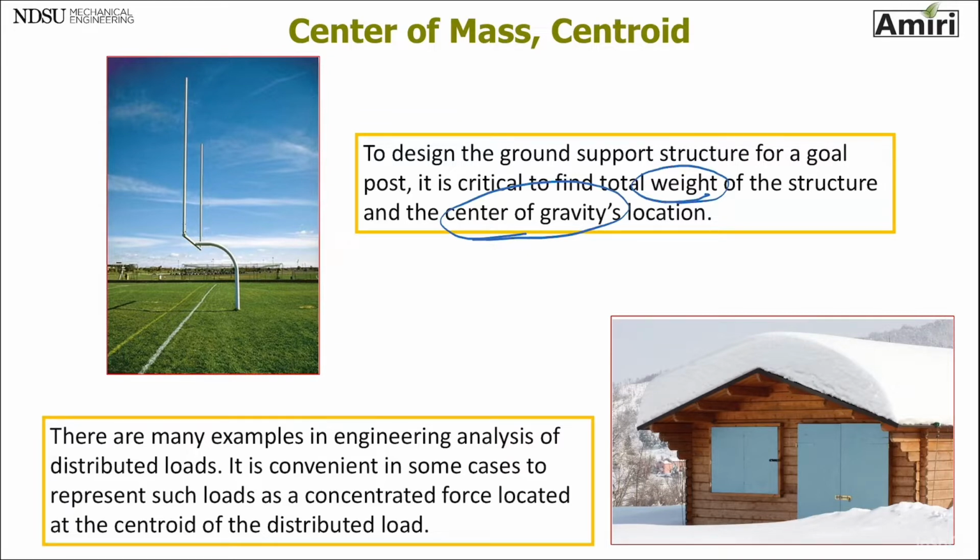Here's another example: snow on the roof of a cabin or a shed or a house. These are good examples of distributed load, and as you can see, it's not a simple area anymore that we can just find the area or centroid of. So we need to use integration to find these loadings.